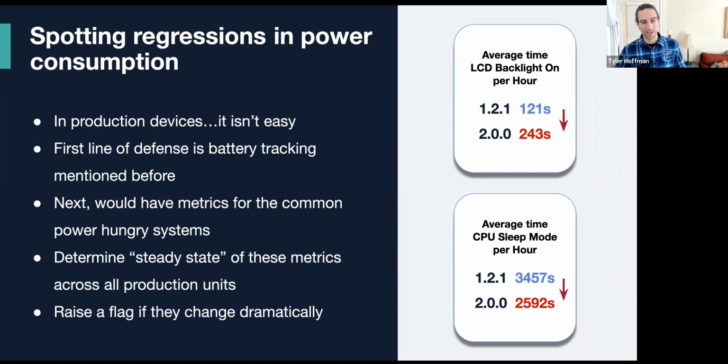Those three things probably accounted for most of our battery life issues, and we would only see them because we were tracking the metrics on that system. If we didn't have the metrics assessing these systems at all times, we probably would have never found those issues, at least as quickly. We probably would have had to hook it up to an actual multimeter, on all the different rails, and then figure it out. But because we had the metrics, we knew, oh, we should be in sleep mode 90% of the time. We were in it 50% of the time. There's a bug, let me go dig in.